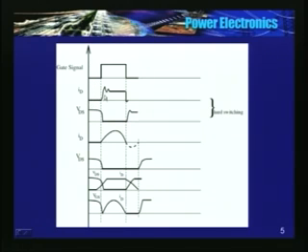There is a current flowing through the device, voltage is falling here. See, if I plot in the same graph, intersection takes place at this point, where voltage across the device is relatively high, it has not attained its saturation voltage. Current has risen to a significant value.